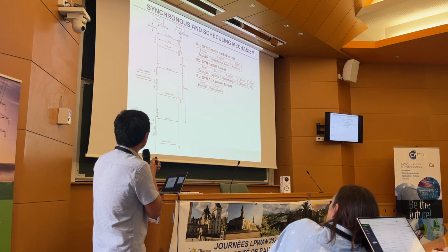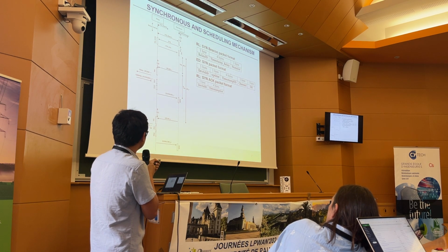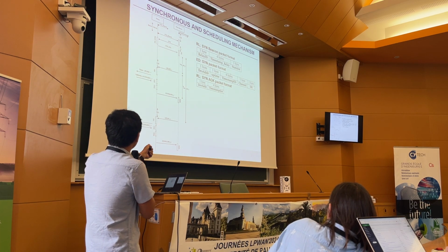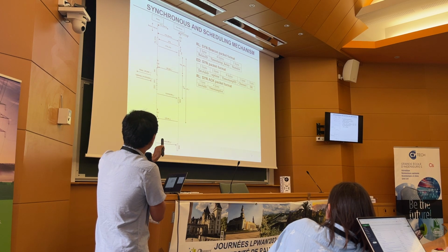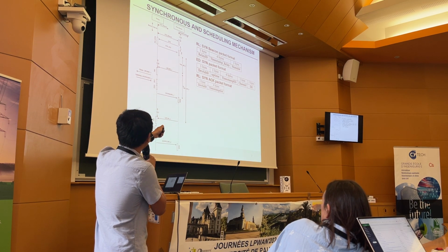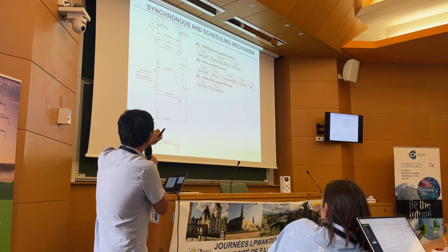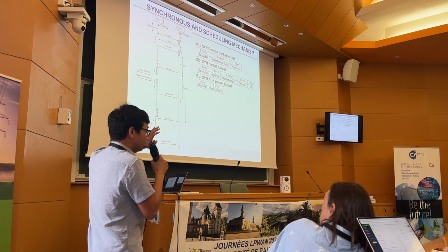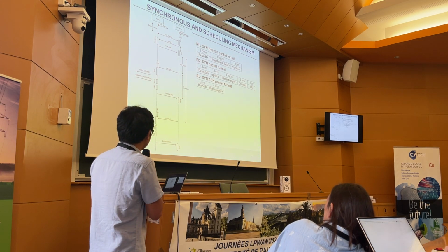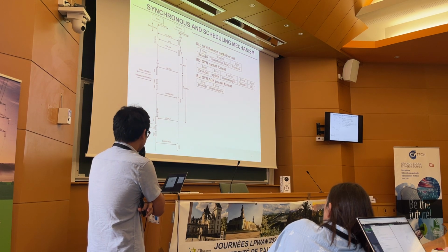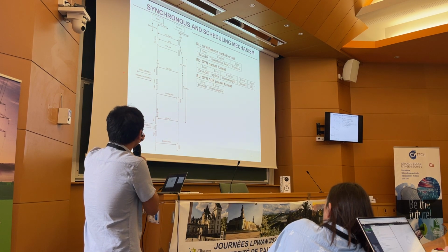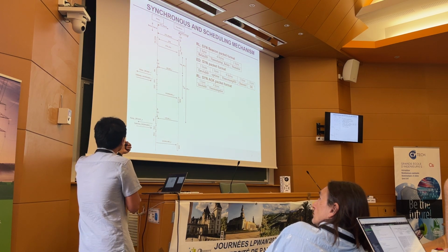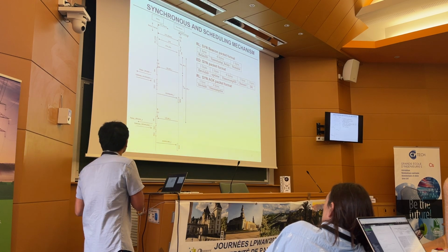Then it works like normal LoRaWAN. We send the opening at this time slot already defined. The end device sends the opening later, but before the time slot, the relay needs to implement CAD to detect the opening packet from the end device, and then they proceed like a normal LoRaWAN packet.